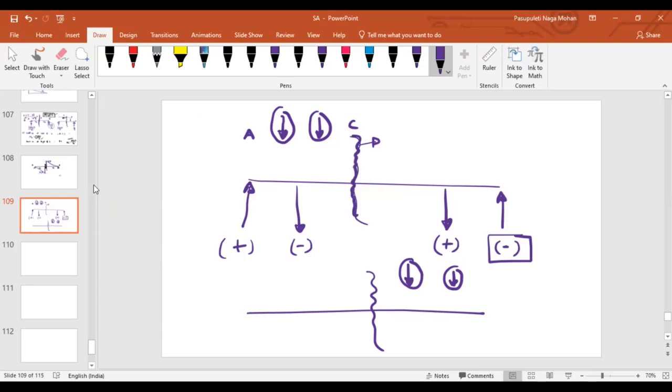Listen, the point is, the shear force at C, isn't it? Yes, sir. Our target is to find the shear force at C, right? Positive or negative, we decide this value based on the position of the load. The position of the load is in between A to C. First condition: if the loading position is A to C, it doesn't matter wherever it is.